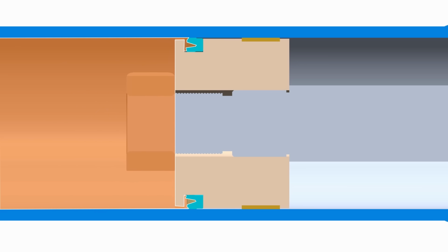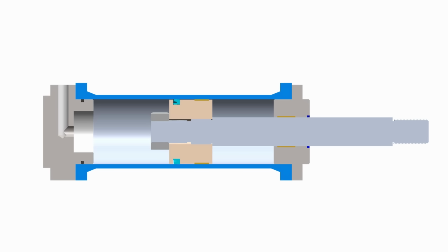The key characteristic of this seal design is that it seals the hydraulic pressure only from one side, the U side. When hydraulic oil applies pressure, these seals expand radially, creating a tighter seal against the piston groove and the cylinder barrel. Therefore, for a single acting cylinder where the oil needs to be sealed from only one side, the U-cap seal is a good choice.